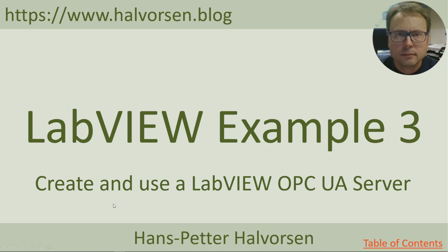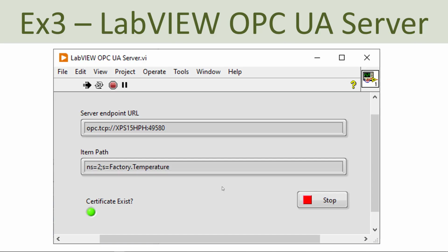So now we will use an OPC UA server created with LabVIEW, and then we will use the same two OPC UA clients created in LabVIEW, in addition to the OPC UA client from Integrated Objects, in order to write and read data between these applications. Here you see the LabVIEW OPC UA server we are going to create. The front panel is very simple. You have the URL for the server, and then the available tags for the server.